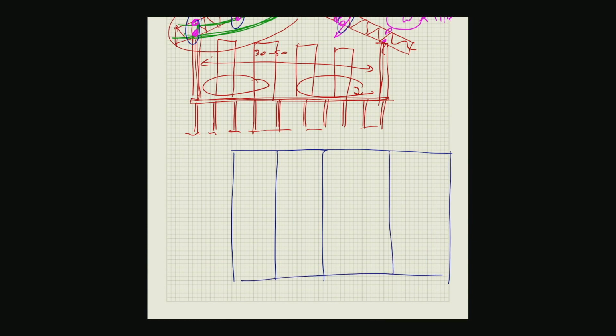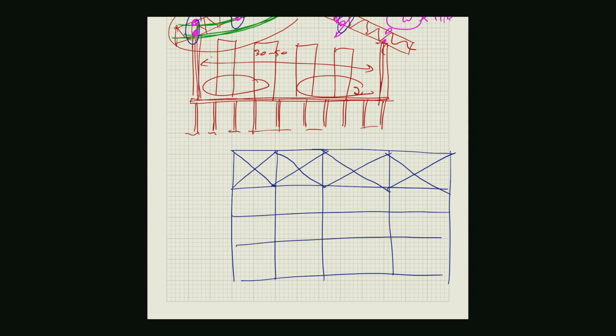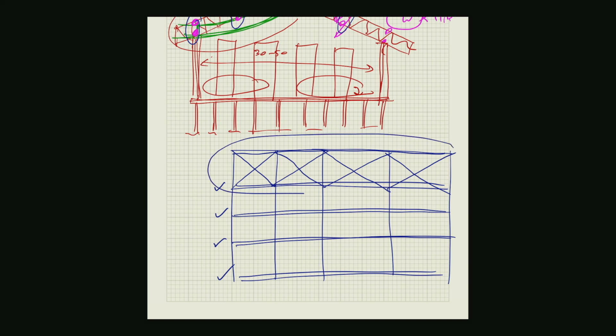Right, this is the top view of the factory, and you will provide the brace like this, as you can see from the top view, to restrain the other roof truss. Okay, so the thick line represents the roof truss. Okay, so the other roof truss will be locked to the panel here.